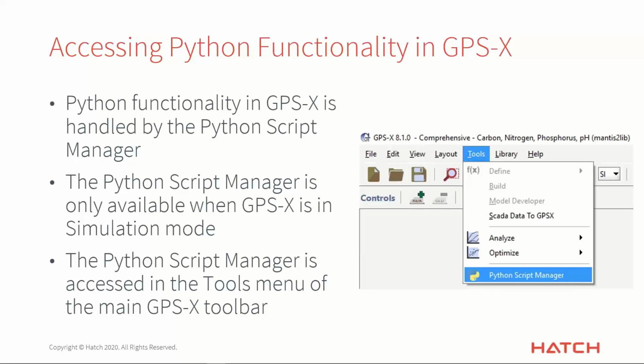So with that, how do you actually get to Python? We made a handy tool called the Python Script Manager that handles all of Python's functionality when you're in GPSX. To get to the Python Script Manager, you need to be inside of simulation mode in GPSX. It's not available when you're in modeling mode, only simulation mode.